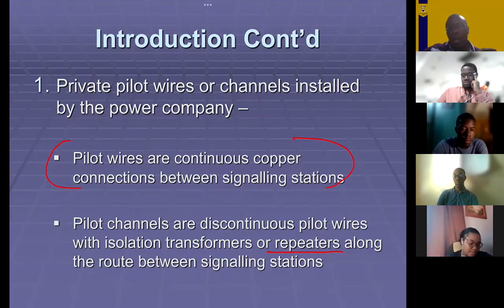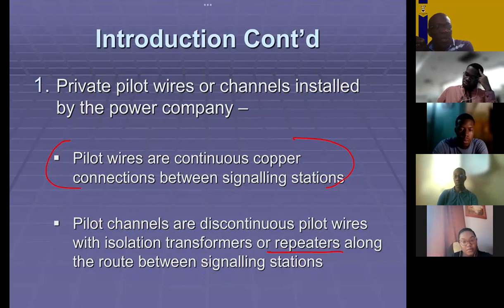So you can have a signal being superimposed on that copper, although you avoid that by using twisted pairs, but you can have noise, which we refer to as unwanted signal, being superimposed on the copper pair. So when it gets to the repeater, unless the value that it sees is above the threshold, it will put it back to 1, because what you want to pass on are clear 1s and 0s. Am I clear?